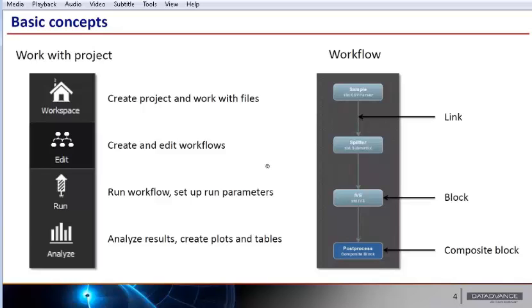The workflows in pSeven are hierarchical, so they can have a nested structure. The projects in pSeven consist of several workflows. Here is the typical sequence of actions that the user does when solving a problem. They create the workflow, add blocks, configure them, and set links between them. Then they choose the input data for the launch of the workflow, and also choose the data that should be saved during the execution for further analysis. After the workflow finishes, data can be analyzed and visualized using plots, tables, and statistics.